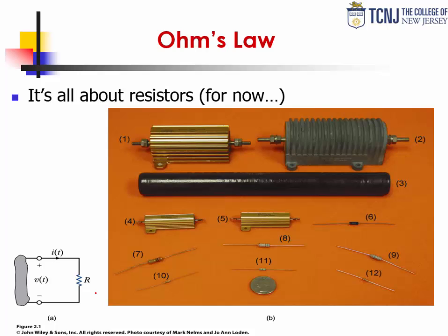The resistors come in many sizes. And the amount of resistance, their characteristic, is a function of the material that is used. Usually they can be of some type of carbon-based material. There is, however, another characteristic to resistors, which is how much power they can dissipate. And that is directly related to the physical size.